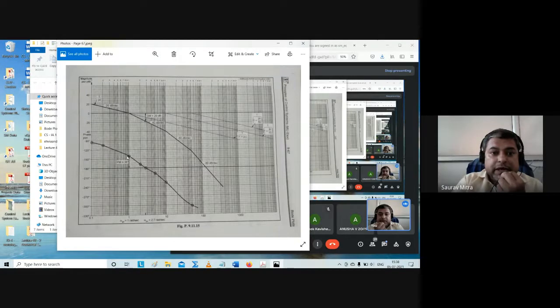Okay, so gain crossover omega gc is happening at 1 comma 0, you have to say that, and at 1 comma 0 we are finding that phase is minus 144 degree. So what you have to say is the phase margin is 36 degree. Okay, so the phase margin is 36 degree. And what you're finding from the graph is the k value does not affect this frequency phase graph, because k is always having a phase equal to 0. Omega gc is 1 radian per second, it is written here. Omega pc is 2.7 radian per second.